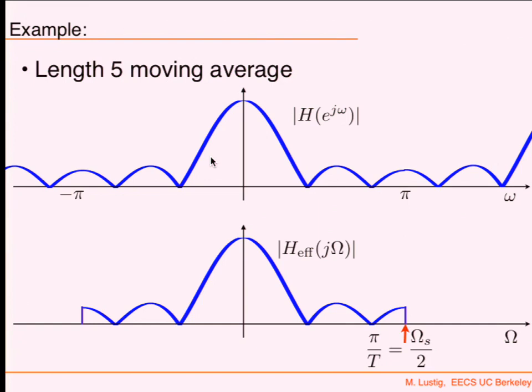But once I put that into the system, my effective transfer function, my effective frequency response is going to be one cycle of the frequency response of the discrete case. And it makes sense because when I reconstruct, I low-pass filter it. Right? I low-pass filter and I crop one replica out of it. Okay? So that is going to be the relationship between those two systems.